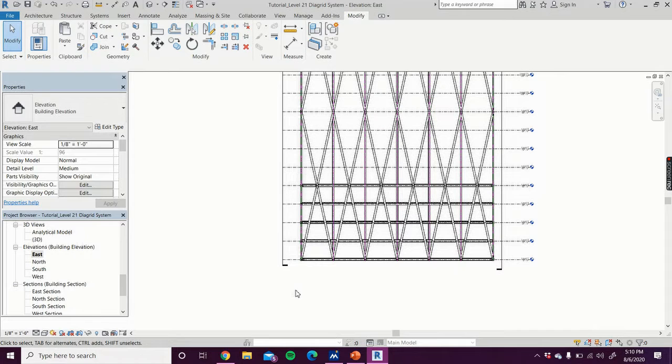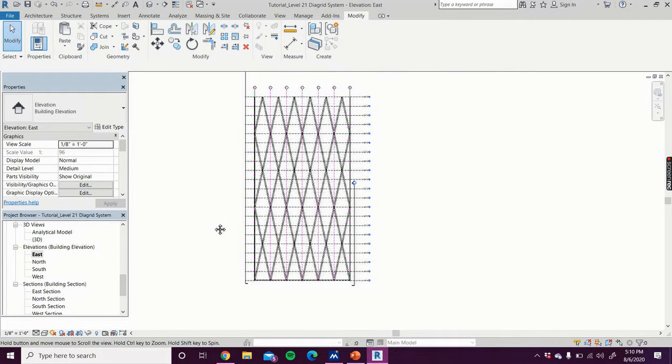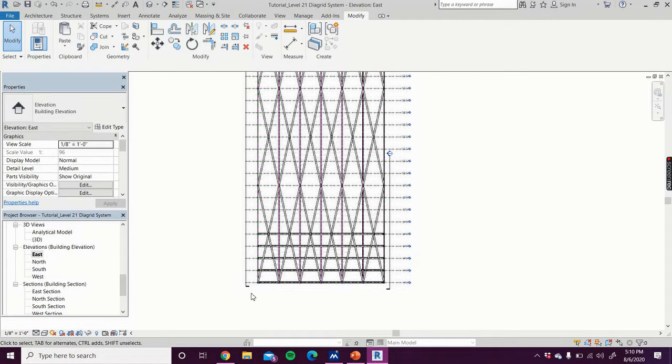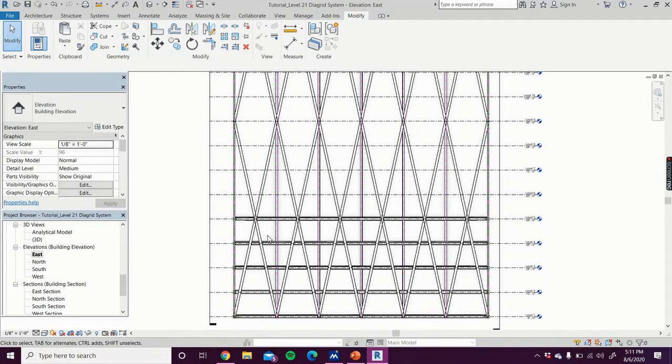So instead of having the same floor all the way up, we're going to have these floors varied, but we're still going to be copying them all the way up. We're just going to be choosing specifically which floors are going to be copied and pasted to. So here, as an example, is the full east side of the building. We have level 2 here. That's going to be going to level 8 and level 10, because as you see, these column nodes all intersect at the same point. They're all 2 foot 6 inches away from the edge here, and that same principle will apply. So floor 3 will also go to floor 7, and floor 4 will go to level 6, and floor 1 will go to level 9.